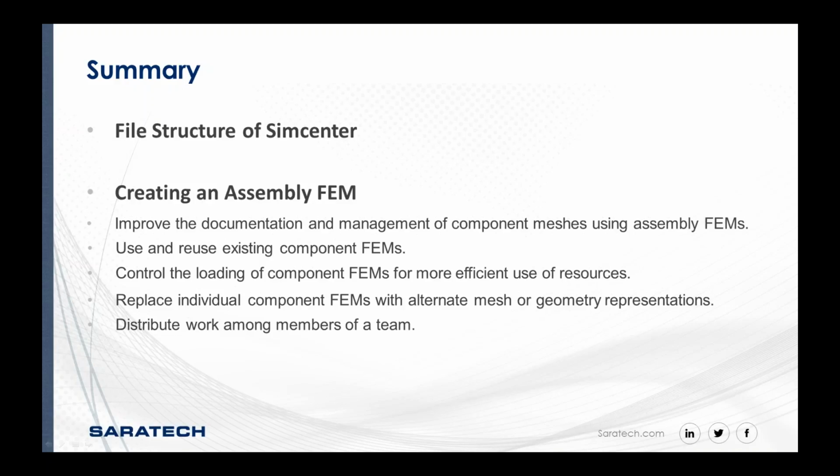Now, in our case, we went through an assembly FEM, which is the same concept, except you're breaking each individual part of your assembly into its own finite element model. So some of the nice reasons for doing these assembly FEMs is it's easy to reuse those little parts in this situation. So if I needed to make some sort of change, or maybe one part has been drastically updated, it's easy for me to go ahead and make these changes.